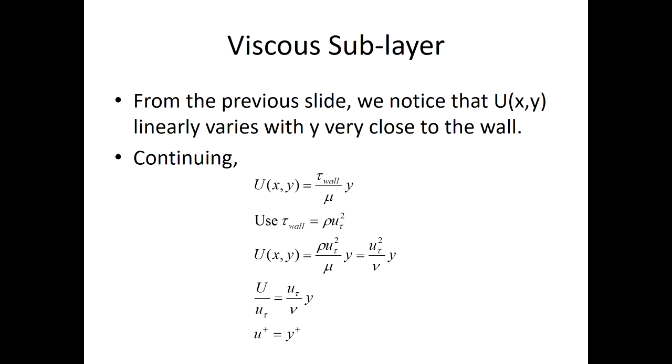Why do we non-dimensionalize everything? Then everything becomes universal. If you plot this velocity dimensionally, depending on the tunnel you tested, this may be 100 meters per second or it may be 10 meters per second. This may be 5 millimeters or maybe 5.5 millimeters. So dimensionally, it's very hard to match one experiment to the other. But if you do it non-dimensionally, you get a nice non-dimensional grouping.